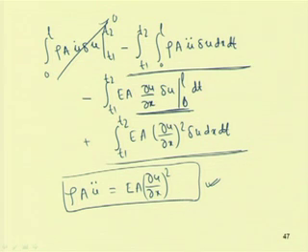So, at the left end, that is the fixed end, either del u by del x equals 0 or u equals 0. So, for the fixed end the slope will be 0 or the displacement will be 0. Similarly, at the right end one can find whether the slope is 0 or the displacement is 0. In that way, one can find the boundary conditions also, in addition to the equation of motion, by using Hamilton principle.